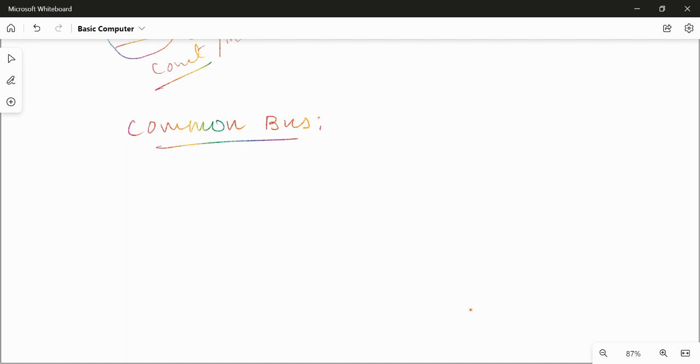So, to design this common bus, we can either use three-state buffers or multiplexers, because the basic purpose is to select a particular source register from which the content can be transferred to one or more destination registers. Here we'll treat the memory unit as a similar entity to a register, because memory and registers are mostly involved in most of the transfer processes.